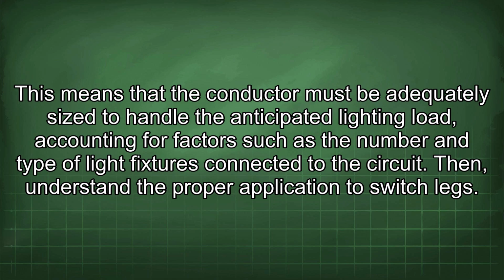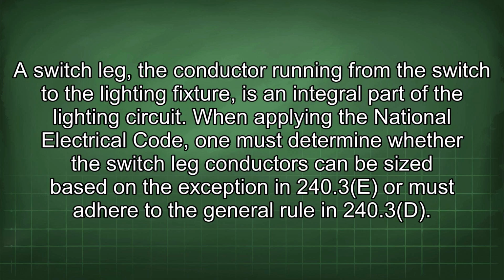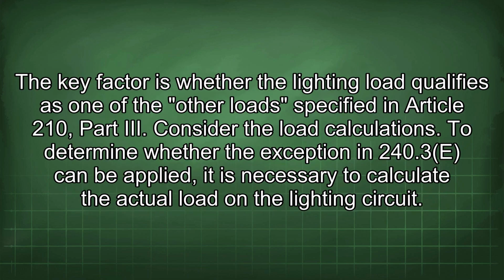Then, understand the proper application to switch legs. A switch leg, the conductor running from the switch to the lighting fixture, is an integral part of the lighting circuit. When applying the National Electrical Code, one must determine whether the switch leg conductors can be sized based on the exception in 240.3e or must adhere to the general rule in 240.3d. The key factor is whether the lighting load qualifies as one of the other loads specified in Article 210, Part Roman 3.